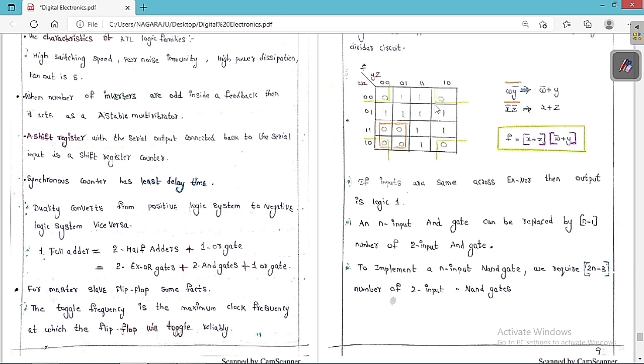So you can see clearly from this K map. Suppose it's a K map like this. F is a function of W, X, Y, Z inputs. W is the MSB and Z is the LSB. So 00 01 11 10 along both axes. So now you can see clearly, I want to mark the zeros, not the ones. So you can see clearly this is one type of zero. So this is one combination, and this is one combination.